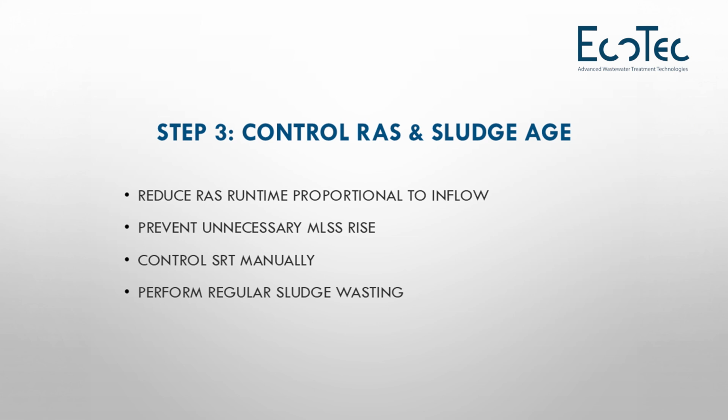If RAS is not reduced, MLSS increases, sludge retention time increases, sludge becomes too old. At partial load, RAS runtime must also be reduced proportionally. Sludge wasting must be disciplined, or sludge wasting should be adjusted. Sludge retention time control is real intelligence. MLSS chasing is only going to end you in trouble.